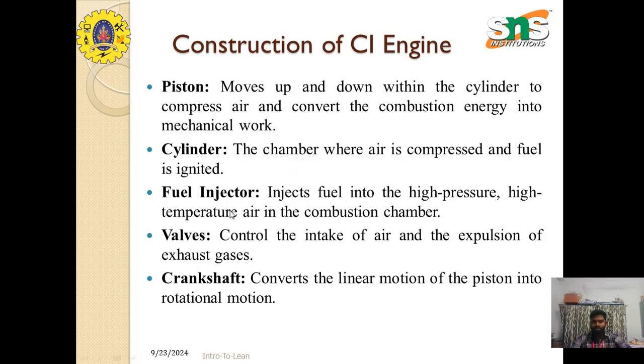The next one is the fuel injector. This fuel injector is a device used to inject the fuel into the high pressure, high temperature air in the combustion chamber. Next, the valves, the intake valve and exhaust valve. They control the intake of air and the expulsion of the exhaust gas to the exhaust manifold. The next one is the crankshaft. This converts the linear motion of the piston into rotational motion, that is, the reciprocating motion is converted into rotary motion with the help of the crankshaft. These are the components present in the engine.